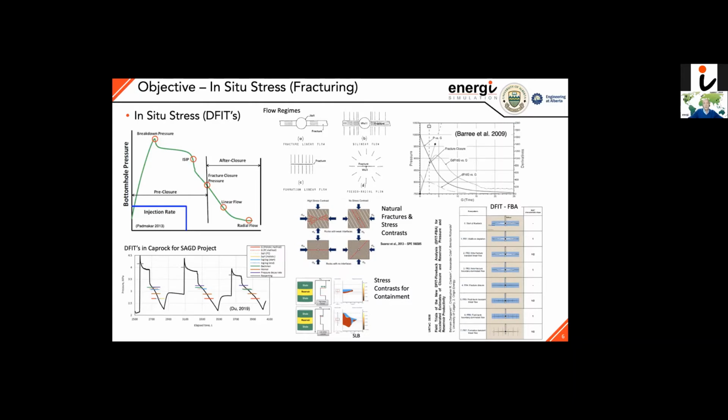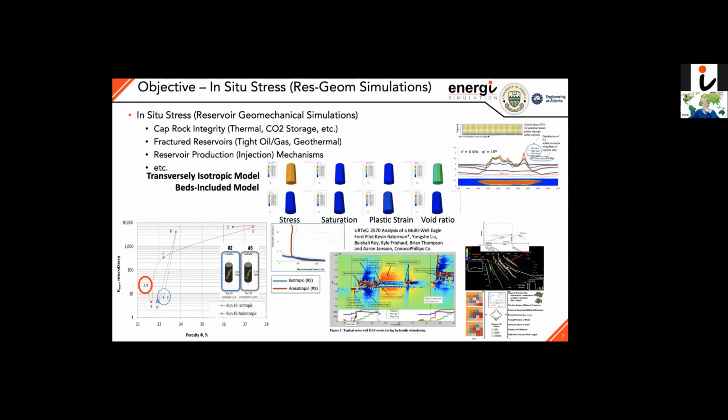What we were interested in was more in the kind of projects that we were taking on. So some of them were, like the ones you see in the bottom left, permanent changes in permeability that were a result of in situ stress conditions. Dr. Griselli talked about bedding features. So issues that we were interested in are issues around imbibition, fluid imbibition in these bedding planes, and those are all sensitive to stress. Caprock integrity, issues around multiple fracture systems in completions for shales, all sensitive to what you assume is the initial stress state.